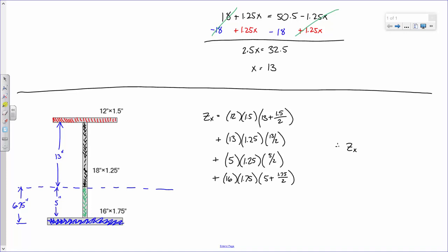And so 533.25. Do I have a second on that? Anybody? Okay, all right. What are the units? This is a section property, and it's specifically a plastic section modulus. And anytime you have a modulus, it's going to be in something like a length cubed. I know I left the units off, but it's basically inches times inches times inches. Okay? So that's going to be ZX.